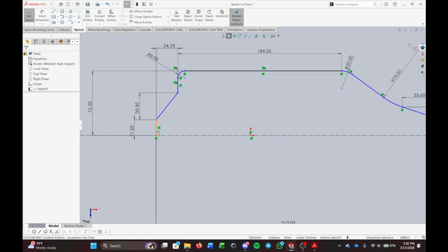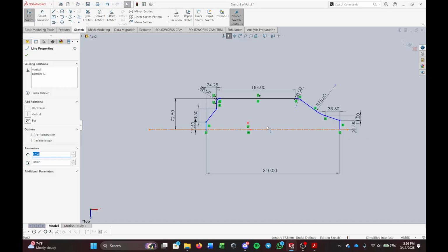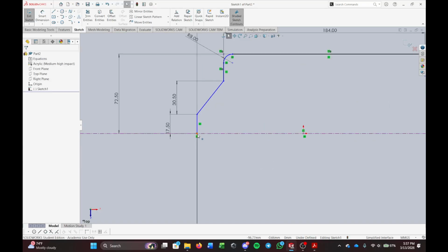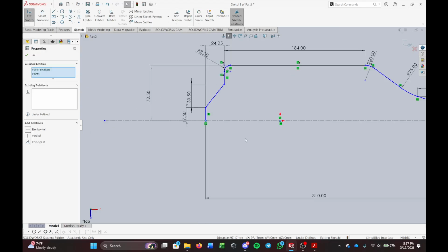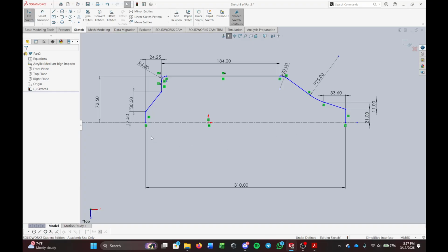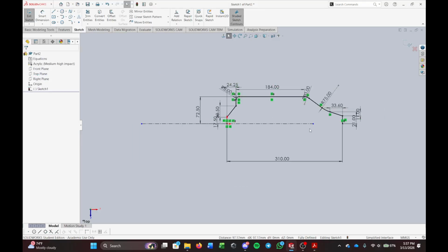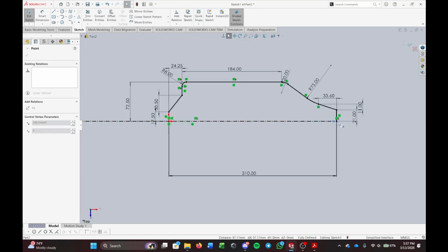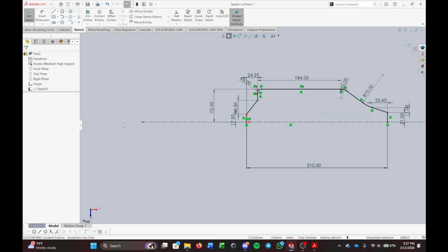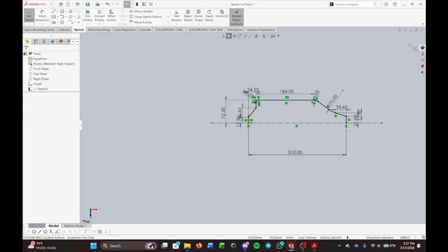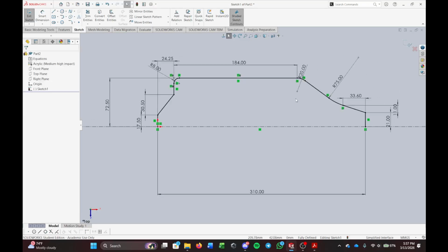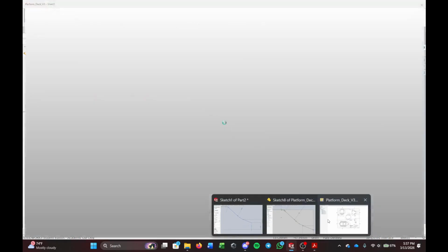So right now, all I'm going to do is align this point. I'm gonna make it coincide with my origin right here. I could do it to the left or right side. I take the left side here, boom, make that coincident. And then as we can see now, everything's solid just because it's related to the origin. That's just a thing in SolidWorks. But yeah, pretty much that is defined.